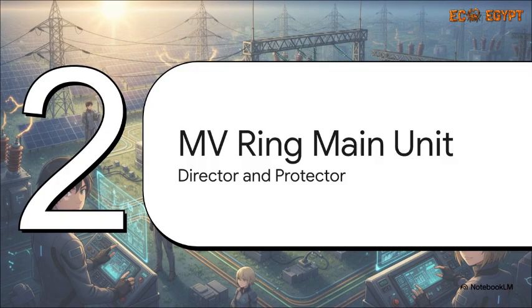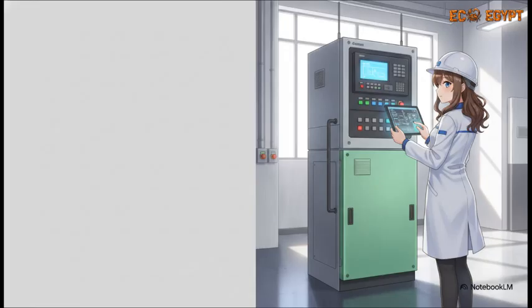Let's jump to Section 4, the medium voltage ring main unit. Heading up to the 33 kilovolt side, we meet the RMU. I like to call this the director and protector of the station. It's a super compact SF6 gas-insulated piece of switchgear. That SF6 gas lets it stay physically small while still safely handling 33 kilovolts and a 630 amp continuous current. It's tough too, with a 25 kiloamp short circuit withstand for 3 seconds. The gas compartment is totally sealed off at an IP65 rating, while the control section is IP54.